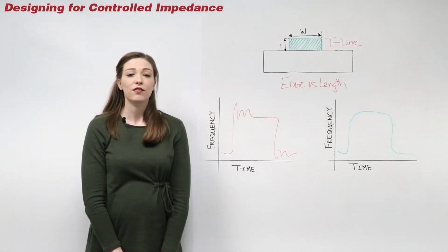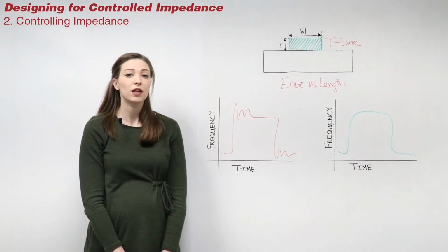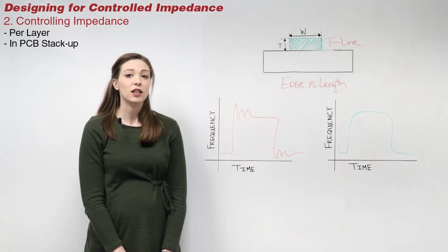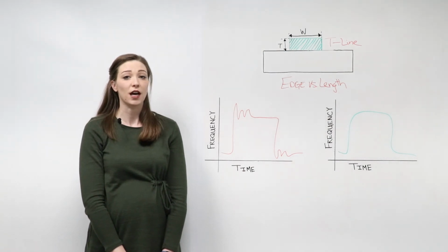Now that you have identified the nets, to prevent ringing and reflection, the impedance can be controlled physically within specific layers in your PCB stackup. You can perform the calculations by hand, or there are many impedance calculators to help save time.